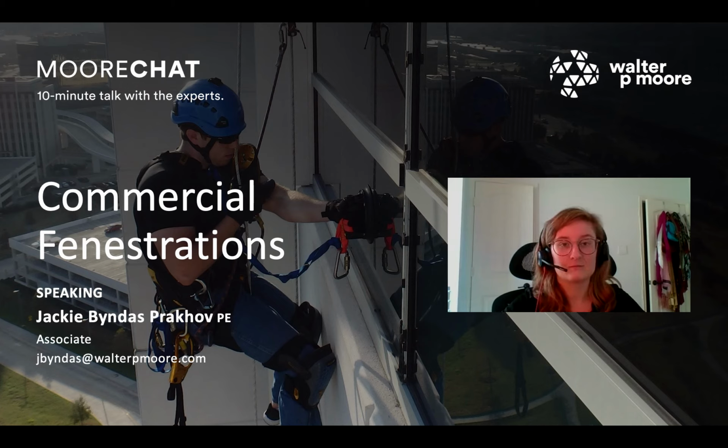Hey, Jackie, this is Faith. I have a question also about window walls. So in a window wall system, can the concrete act as the air barrier as well? So the concrete can act as the air barrier, but for any moisture that may be trapped there, it is recommended to add some sort of membrane at that location so that you can get it wicked away from the concrete to prevent it from migrating.